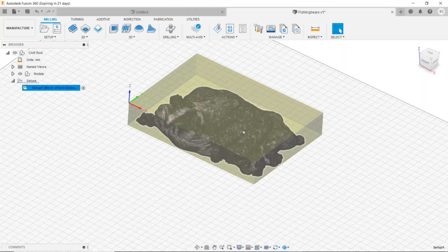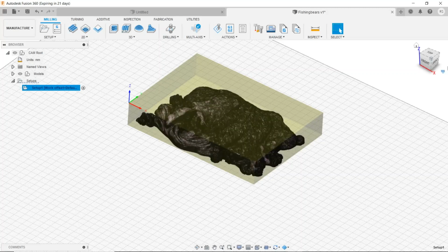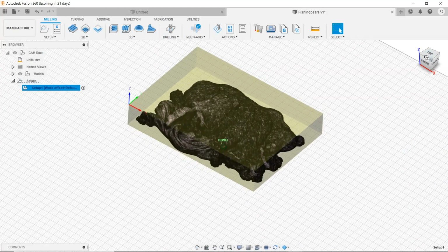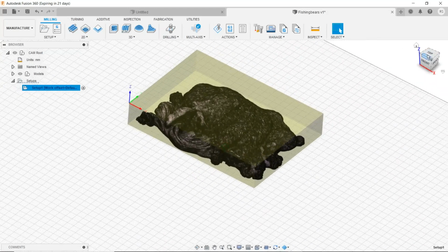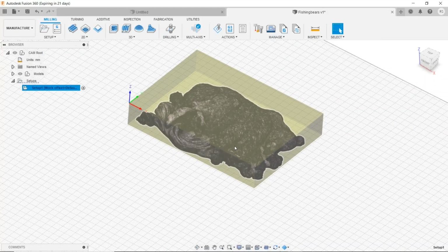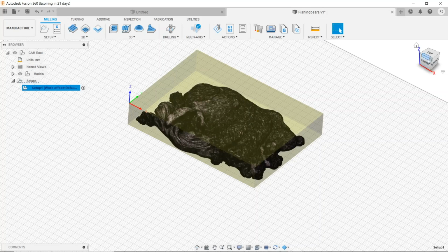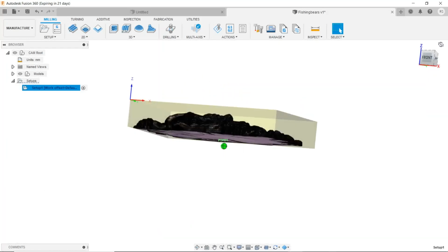Now it's time to do the dirty work and add some tool paths. The tool paths for this kind of cutting are going to be two types. You're going to have some type of a roughing, and then you're going to have some type of a finish. Basically, this is a 3D shape because you've got your length, your width, and then your height.